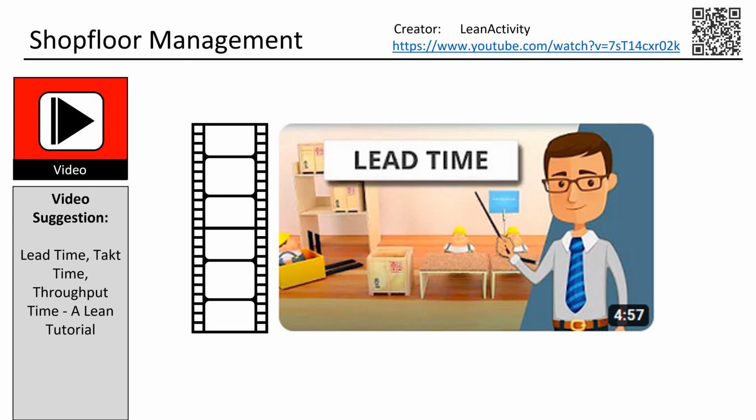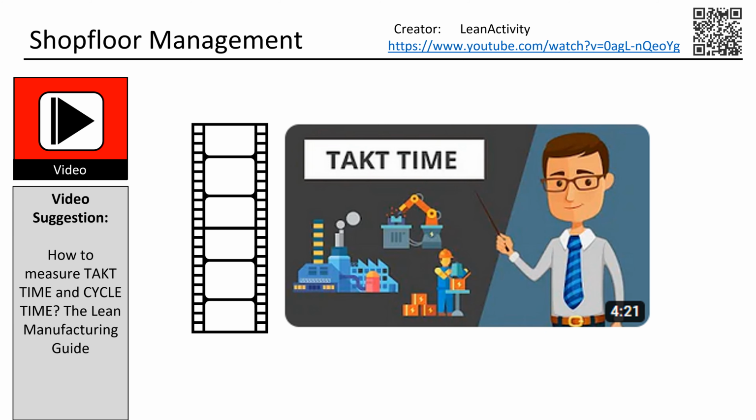We will focus on lead time, also called cycle time. This concept is most important for you. The cycle time always works in interplay with takt time. These time concepts need to be understood if one wants to work customer-centered. Please make some effort to understand these time concepts. They approach your production process from both sides. Without understanding this concept, you will for sure create waste.